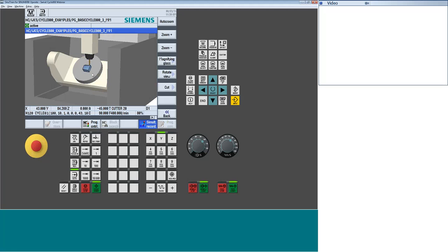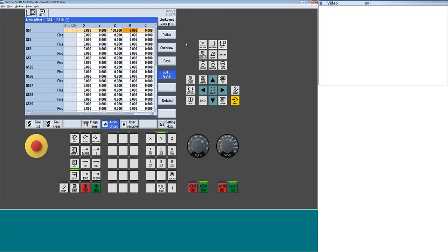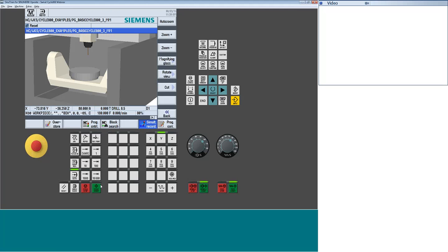But what happens if I had positioned her when I threw my vise down and whatever fixturing or whatnot at a position, and let's say I did, I don't know, let's do 100 here. 100. All right, some crazy location. Oh, I immediately see I got an over travel software limit switch. Now, this is a problem. This is certainly a simple scenario, but I might have been down in a pocket. I might have been in this weird location when this over travel occurred.